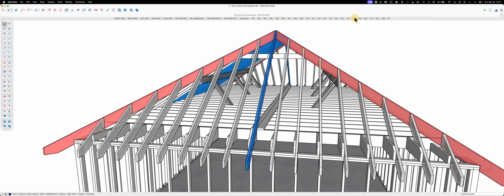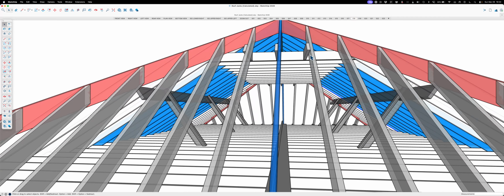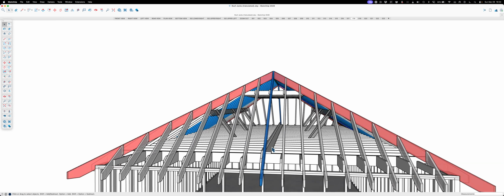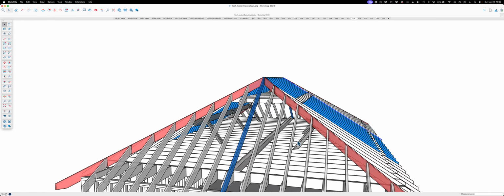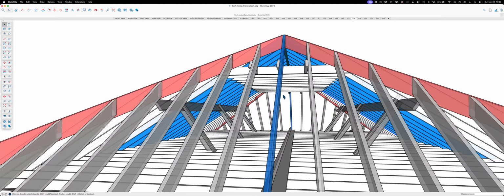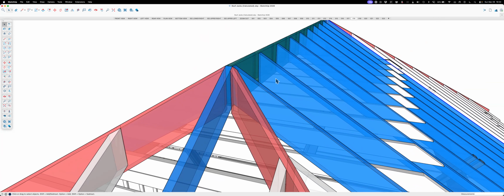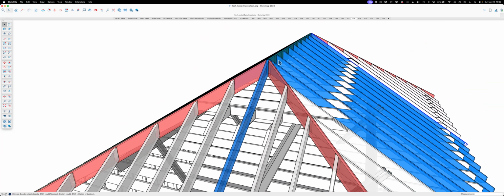And then collar ties. So collar ties, the code actually has like 1/3, 2/3 of the attic space where these are all allowed to go. Like if you had joists that were raised, going from rafter to rafter, it has to be in the first third of the roof. And then in high wind zones, we also did wind ties, which are like collar ties, but they go straight across, barely underneath, like they'll touch the ridge and come across the other side. And that would be like every other rafter would get wind ties.